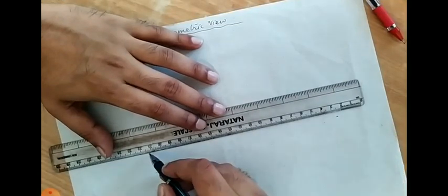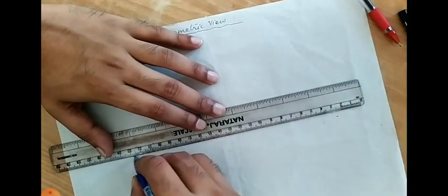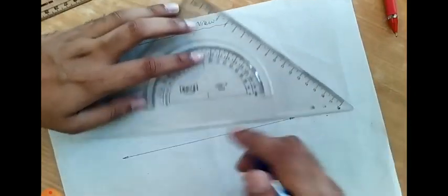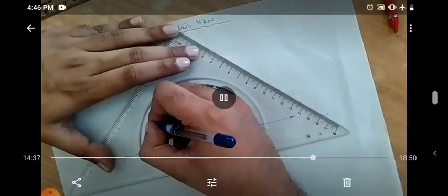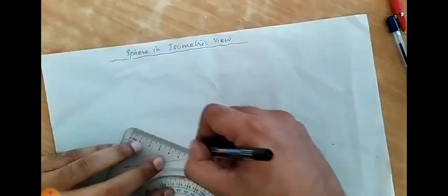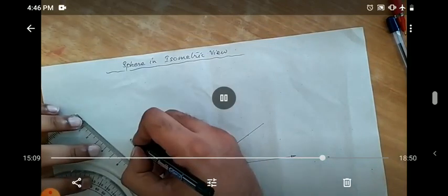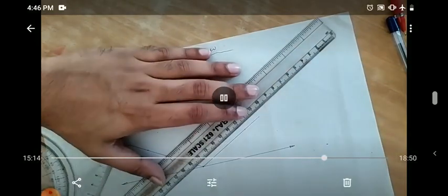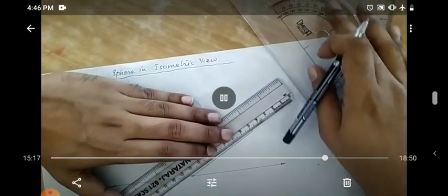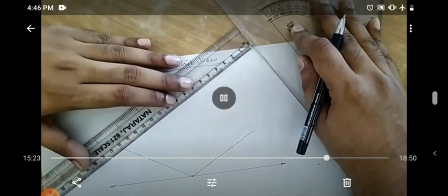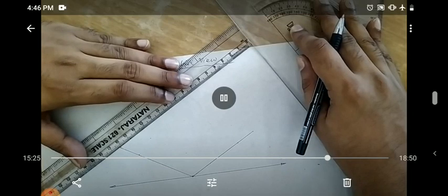So at the start, similarly we have to draw the orthographic projections, the top view and the front view. After that, while drawing the isometric view, the first step is taking a horizontal line, then marking a point on the line and creating the two isometric axes. Now on the axes we have to represent the two edges of the square plate. The square plate has an original dimension of 75 mm. As we are drawing the isometric view, the dimensions of the square plate will remain as 75 mm itself. It will not be changed.